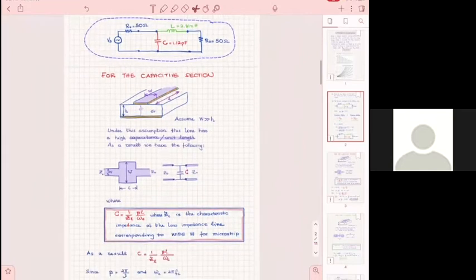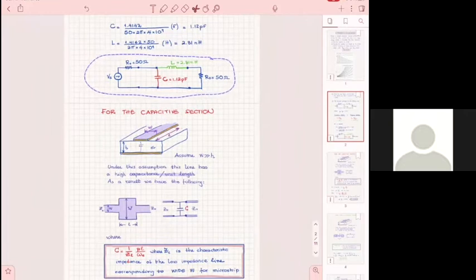So now, what do we do next? I asked you to find the impedances, which I gave you. When somebody tells you to design a filter, a low pass filter in this case, and they give you the lowest impedance you can use and the highest impedance, and they tell you it's a stepped filter, you know you have to use sections of lines.